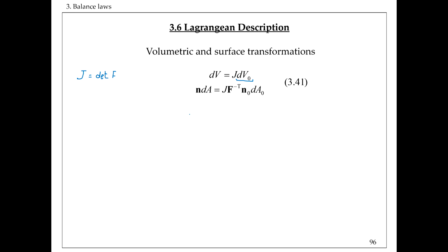So in a similar manner, we use the Nanson formula, right? So that is related as the Nanson formula, the Nanson equation. We related the area element n dA in the deformed configuration, where n is the normal to that small area element, to the n0 dA0 area element in the undeformed configuration.